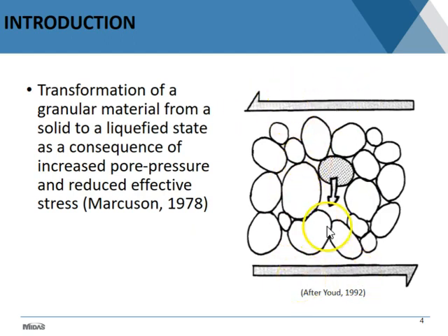But when this material is also saturated, when the shaking comes in and these big arrows try to show that type of deformation that this soil mass can have, the particles tend to reaccommodate, and as they try to move and fill in these spaces, they find water. And the water, within the number of seconds where you have the earthquake happening, cannot just flow and move away of the path of this particle.